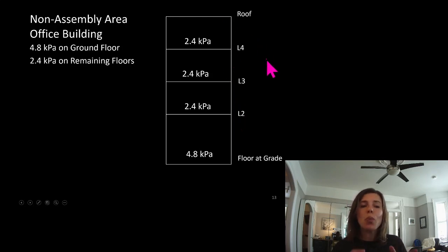This is important because we're going to do exercises where we figure out the loads on these columns. And I know most people are thinking, why are you explaining this to me? But for somebody that's never actually had the opportunity to think about it, every year this catches 4 or 5 people out, and they get really frustrated about it. So I just wanted to take the time to explain that right now. This column here, or the column from level 1 to level 2, isn't supporting level 2. It stops at level 2, so it does not have load on it from level 1.